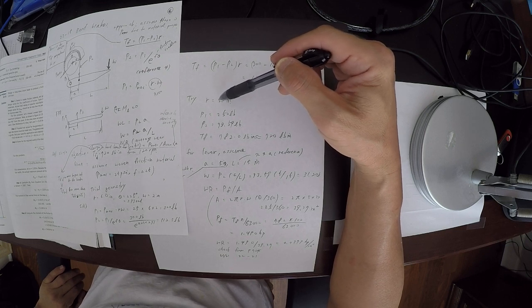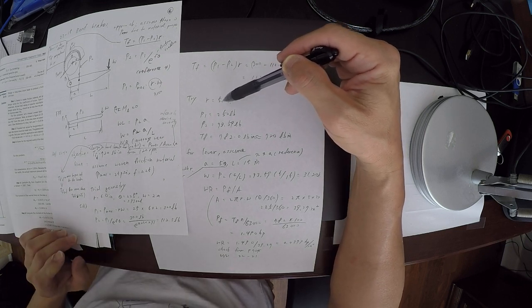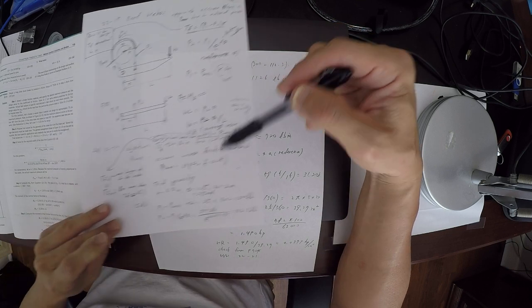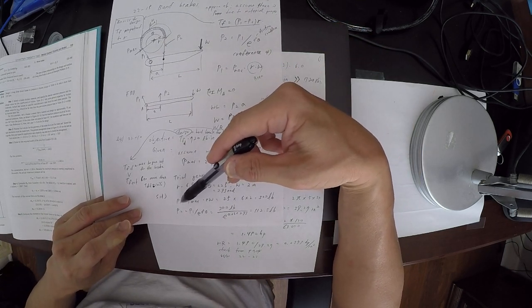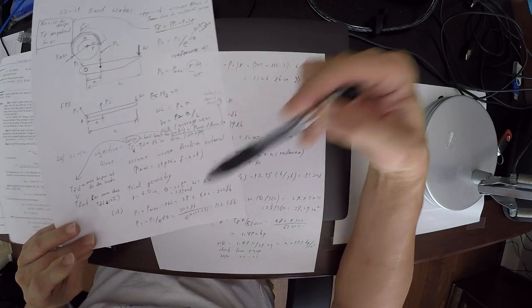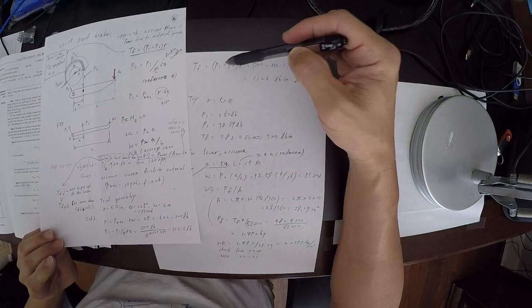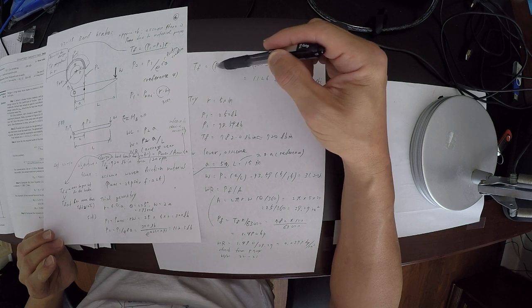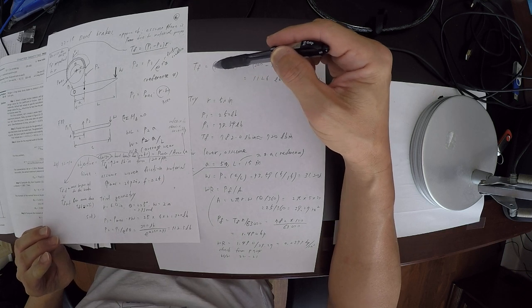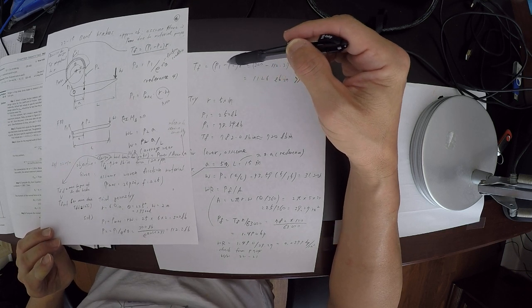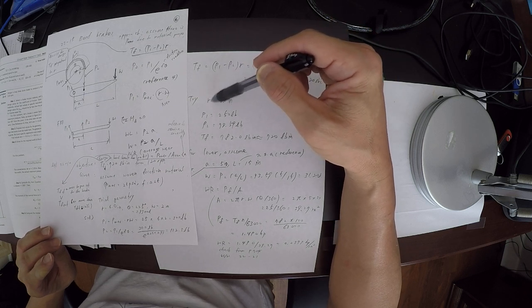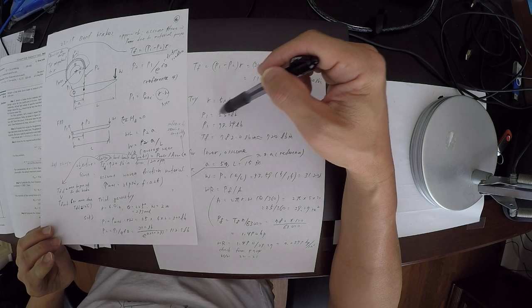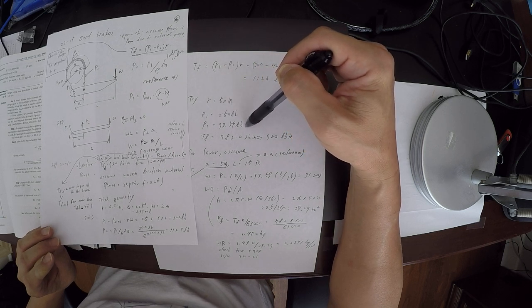If it's 5 inch, then R is going to be smaller, which means that P1 is going to be smaller, and P2 is also smaller. Because P1 is smaller, TF is supposed to be smaller as well. So by reducing the radius of the band brake drum, you will have different numbers for P1 and P2.